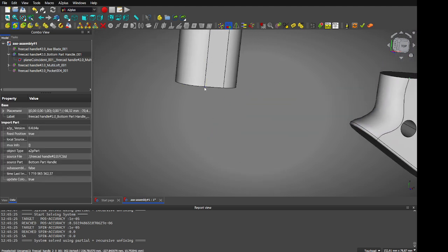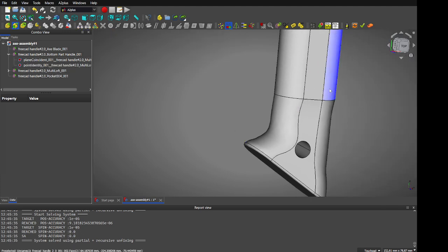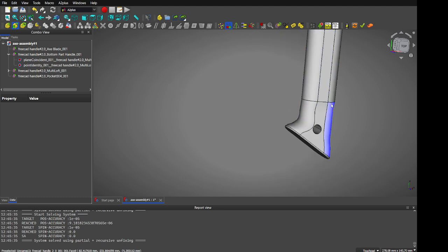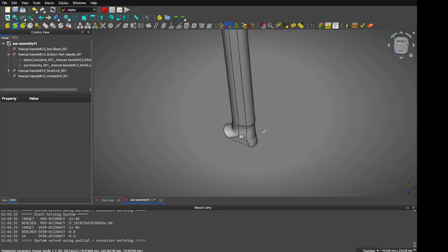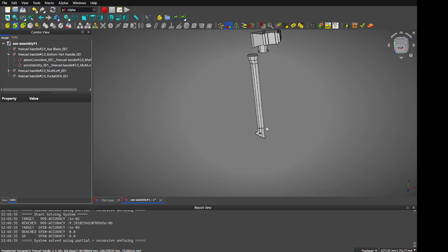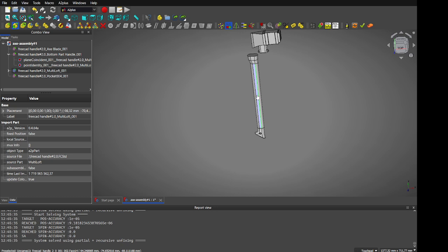And now make point-to-point constraints. So click point-to-point, and you see that this is in one axis, so connected into point-to-point. The integrity of the part you can check by clicking on the element and moving it, but it can move only when it's not set up as fixed. This is fixed, so the only part which can move here is this.